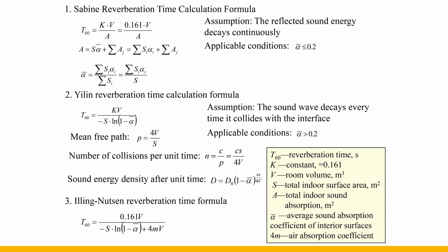The three calculation formulas of the reverberation time are based on a fully diffused sound field and a complete space, but in fact the interface materials in each room are different. This makes the indoor sound absorption unevenly distributed, resulting in different attenuation speeds in all directions, and there may be more than one space with a different attenuation rate. Therefore, the attenuation curve on the decibel scale is theoretically a straight line, but in practice there will be a zigzag. The calculated value of the reverberation time will deviate from the actual value.